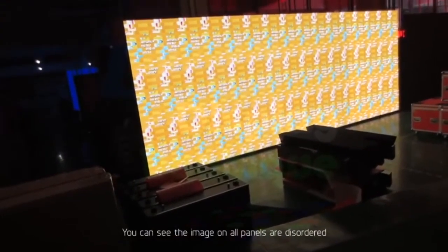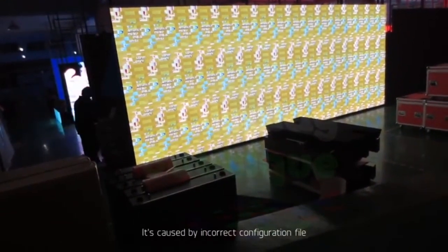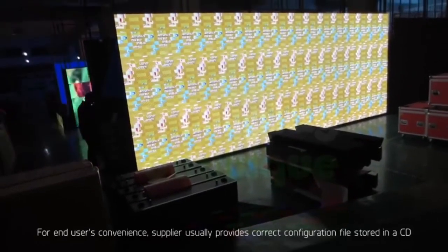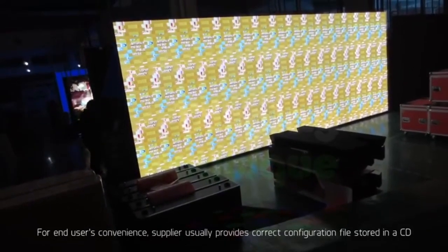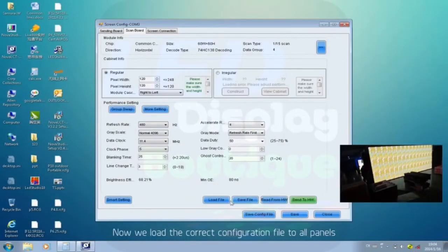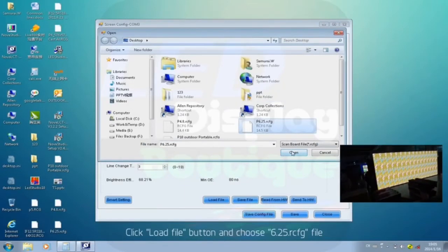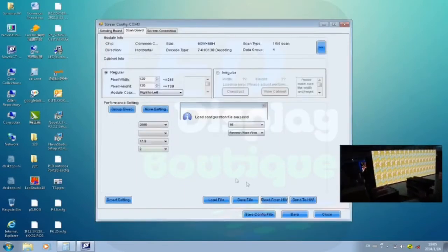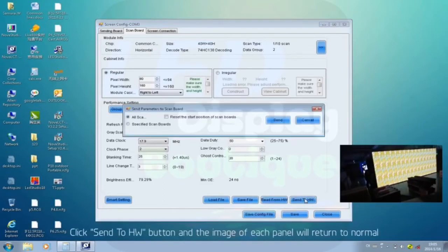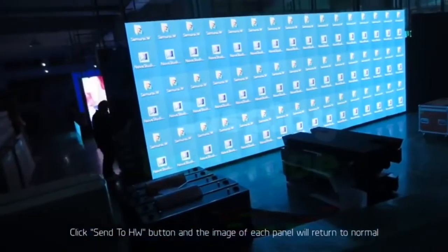You can see the image on all panels is disordered. It's caused by the incorrect configuration file. For end users' convenience, suppliers usually provide the correct configuration file stored on a CD. Now we load the correct configuration file to all panels. Click the load file button and choose the 6.25 RCFG file. All parameters return to previous values. Click the send to HW button and the image of each panel will return to normal.